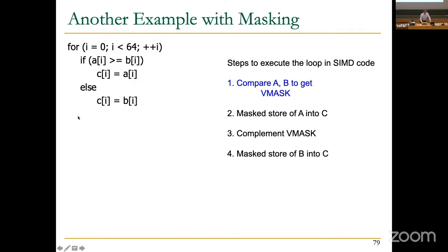And then once you go out of this loop, let's say, you set the V mask to all 1s. And this is what you do. So you can actually do operations on the mask vector also. So basically, you're doing predicate computation on the mask vector. This is very powerful. In fact, the ARM ISA had conditional execution a la these processors, but then they got rid of it because it was very difficult in a scalar processor. But in a vector processor, it makes a lot of sense because it gets rid of these branch instructions completely.